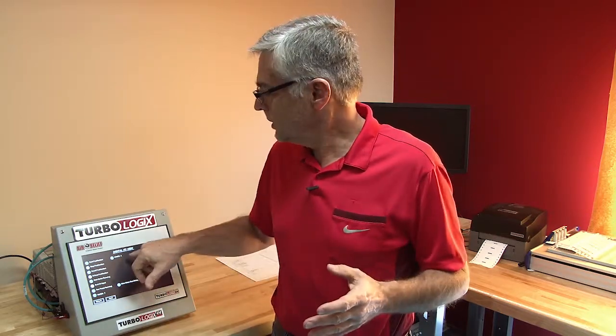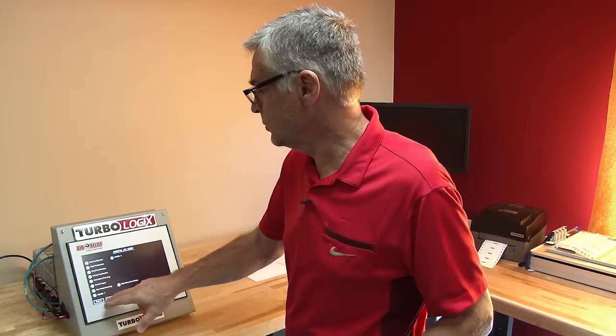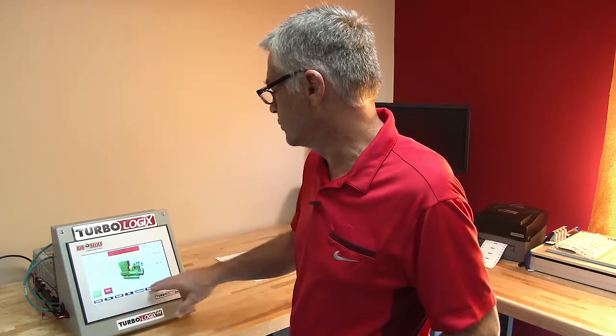Okay, since I've programmed that input there, that information, number 7 and number 8, that tag will propagate throughout the whole system, right? So my digital I/O view, it shows up there, and it will also show up in my event log. So if I have number 7 or number 8 that goes out of tolerance, and I have a trip or alarm, depending on how I have it set up, then I will have an event log item that will say number 7 or number 8, trip or alarm. Okay, so that's kind of what we're doing here with that part of the digital screen.